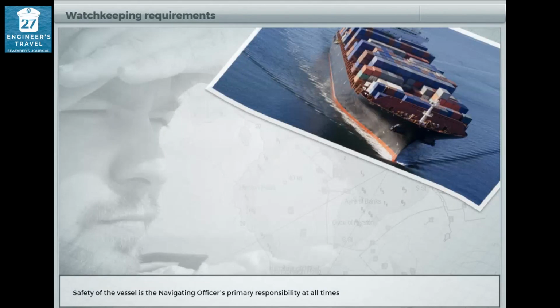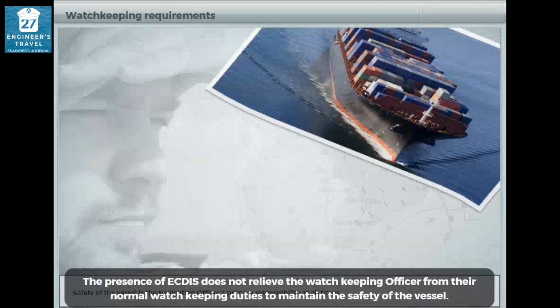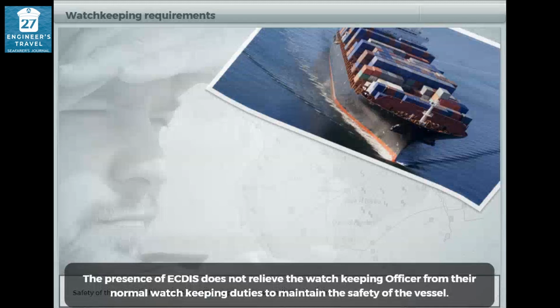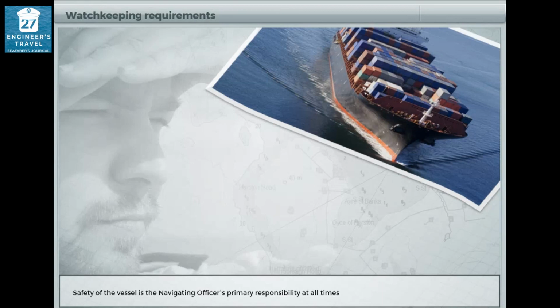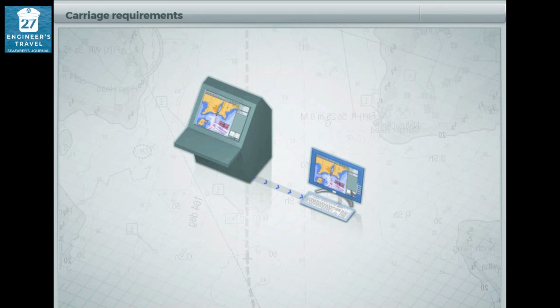The presence of ECDIS does not relieve the watchkeeping officer from their normal watchkeeping duties to maintain the safety of the vessel. If navigation is totally or partly performed on ECDIS, there has to be an independent backup system available. There are two main reasons for this.